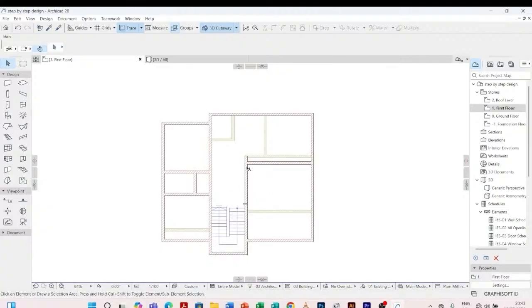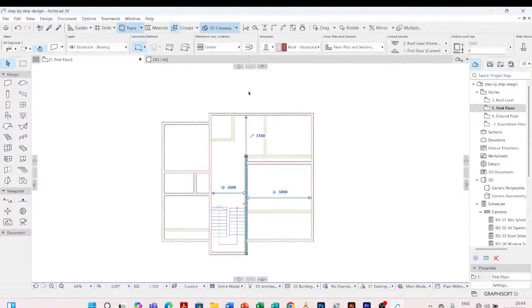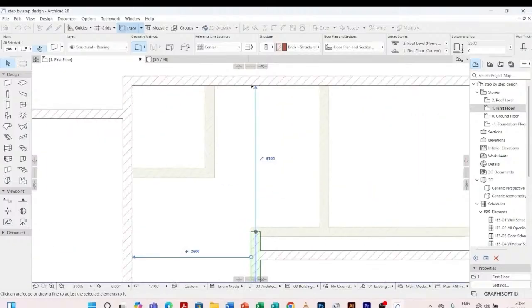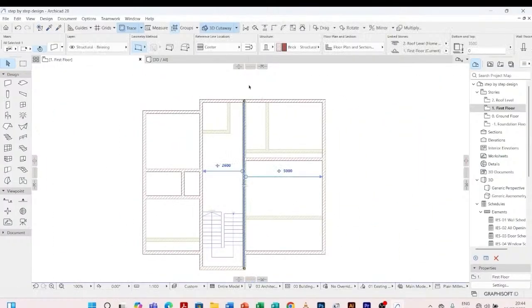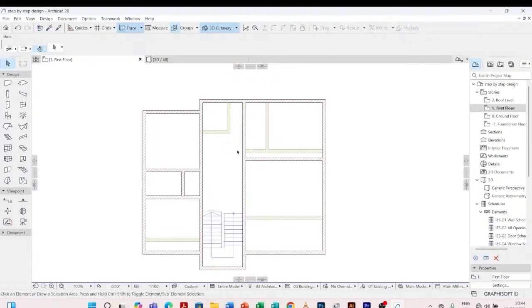So this will come all the way to join here. So I can click on it. I come and extend or adjust. I want it up to the middle. Since I'm using my walls as middle, I have to come and pick from the middle. So for this other room, I'll access from here. For the master bedroom, I'll access from here.